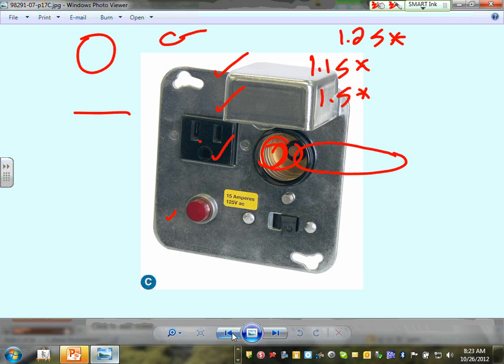Is that current? Do we actually still use S-type fuses or something like that? Yes. Or is that an old picture? No, you can still use S-type fuses for this. Absolutely. I didn't think anybody did. This is a supplemental, non-dwelling, supplemental overcurrent protection. Supplemental. I emphasize the word supplemental for better protection.